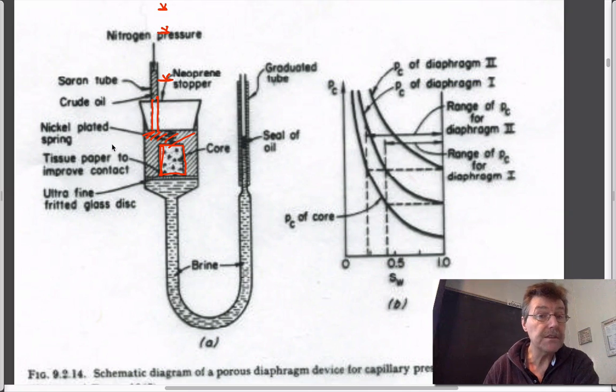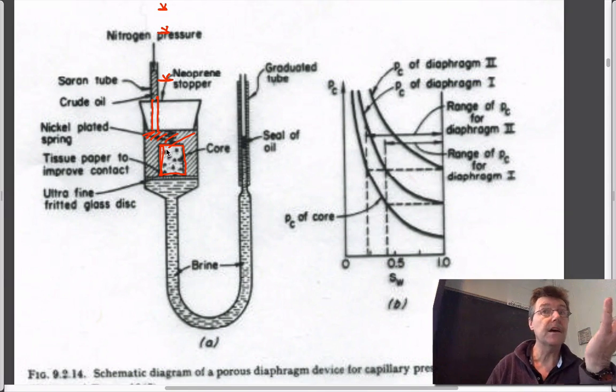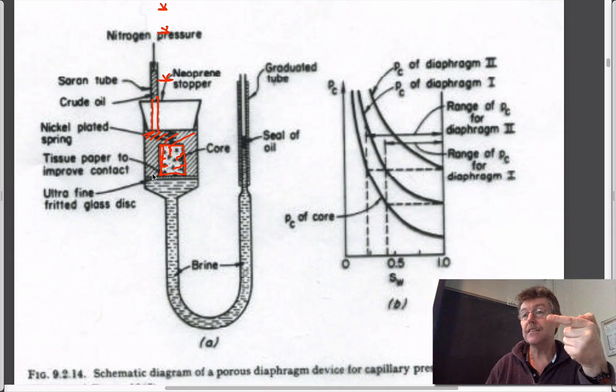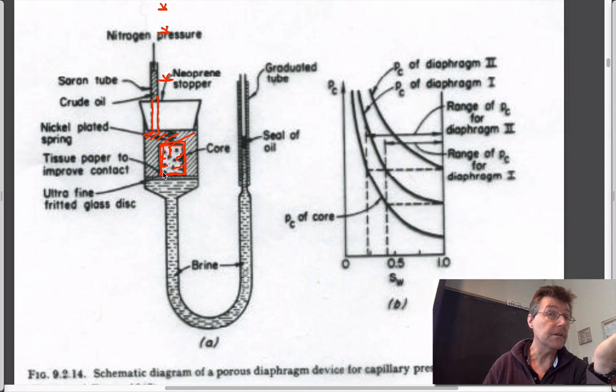And what you'd expect to happen would be exactly the same as we saw in that diagram with the invading red fluid. Initially, when it's not high enough, you don't get anything in it. When you increase the pressure enough, you'll get some little invasion on the edges, so that within these little slithers, it's 100% saturated with the NAPL, the red fluid, but outside that, it's 100% saturated with water. But if you take it on average, on aggregate, then maybe it's 5% NAPL saturated and 95% water saturated.